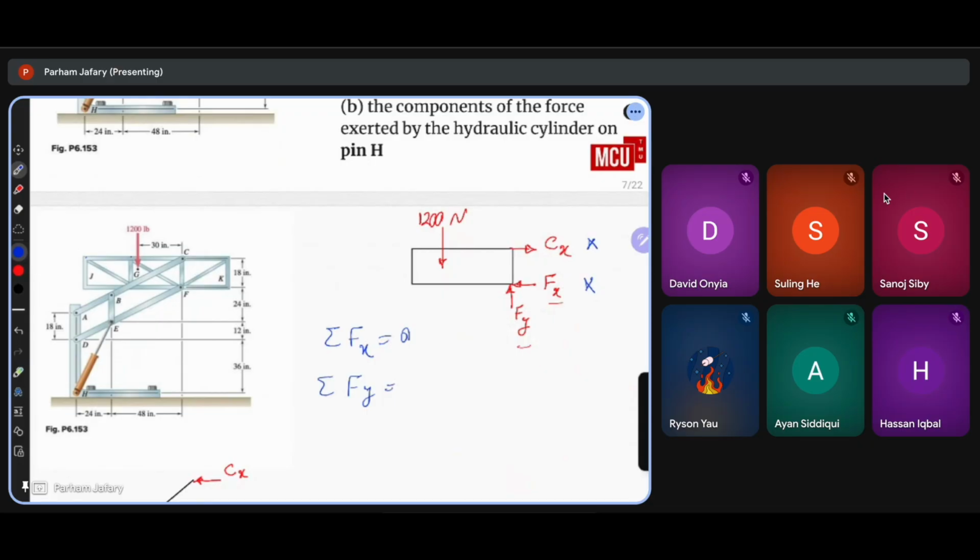So you always calculate the moment around the point that has two unknown components, obviously, because in that way you're only left with one unknown and you can solve it through the equation, right? If no such point can be found, then you're just gonna have to solve a system of equations, like 2 equations, 2 unknowns, or 3 equations, 3 unknowns, okay?